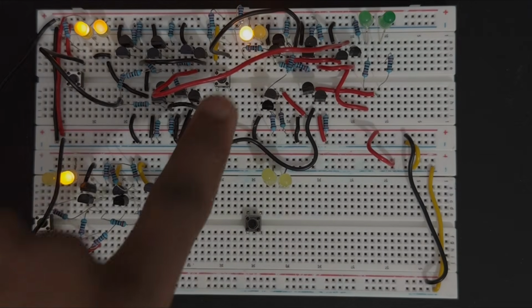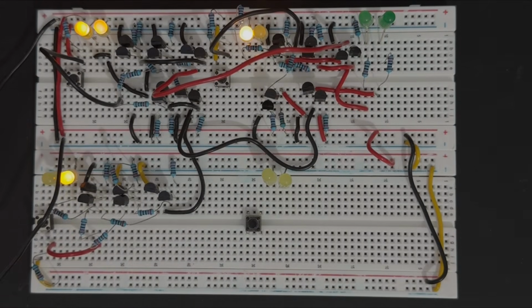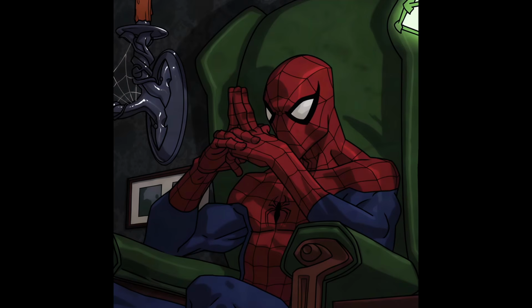If none of the devices are enabled, then none of them output their values to these wires. They are all disconnected from the circuit, and there's no limit to how many devices you can connect up here. If you connect 16 billion registers to the same 8 wires, I explained how registers work in the last video, and control their outputs using an address decoder, which is just a circuit that selects exactly one register at a time, you've made 16 gigabytes of RAM.